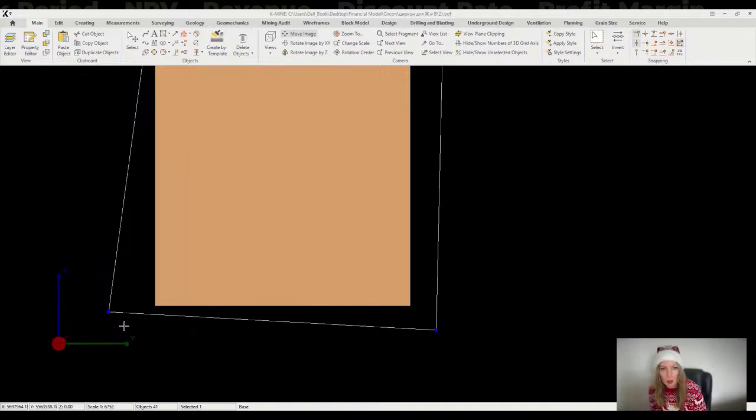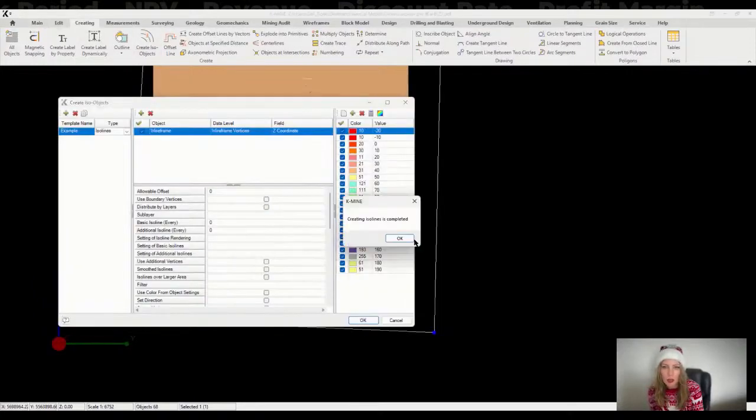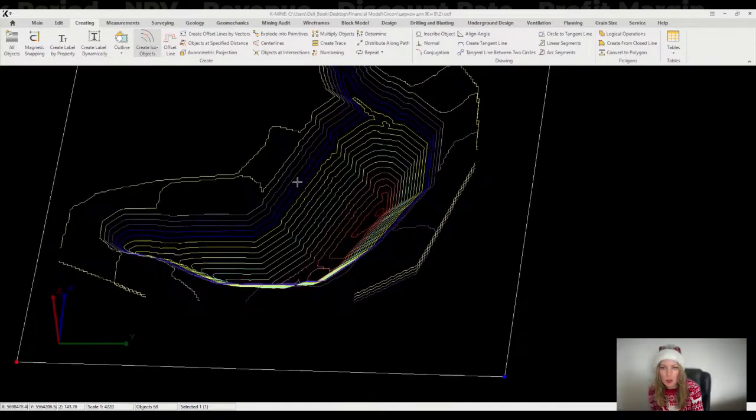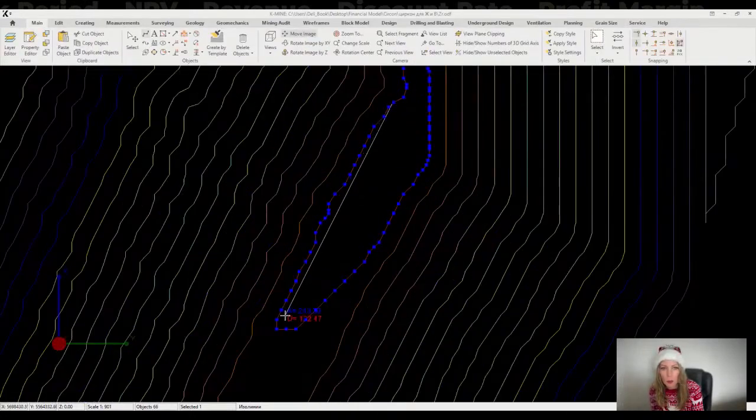Dynamic design is a key component of our design model. It's incredibly helpful for quickly and efficiently shaping the final outlines of pits and other major pit elements. Usually, creating this manually can take ages. So when you start working with the plugin, the first step is to get some guiding lines. You do this by using the command to create ISO objects. In the settings, we'll specify elevation marks, and then the plugin will generate ISO lines all along the frame height. It's a real time saver.